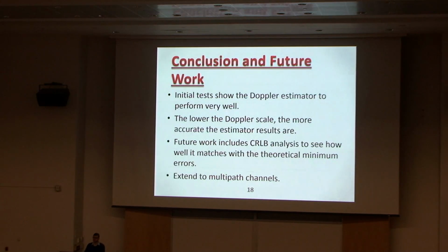So you said they will be shifted out in the carrier. When you filter out your carriers, do you use two? No, when I filter out the carrier, the frequency offset will remain. It will not be mitigated by the Doppler. The Doppler shifts the frequency by a value A times FC. The down converter only down converts by FC, so A times FC remains. We can't down convert by A times FC because we don't know it, so we are forced to down convert by the same carrier.